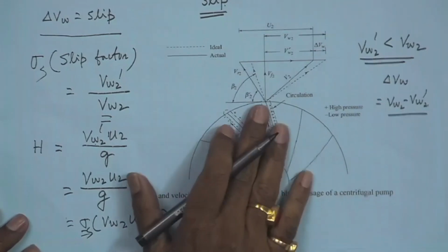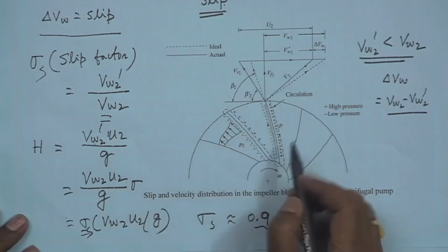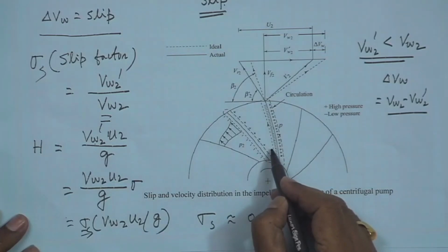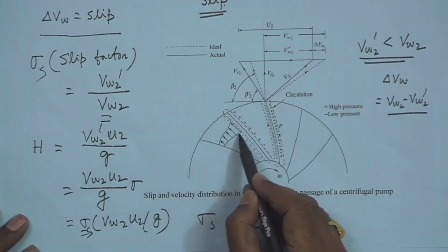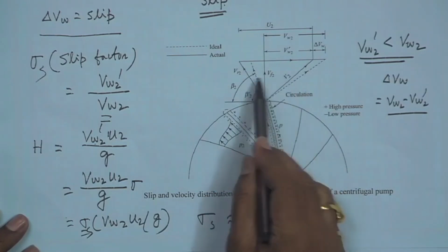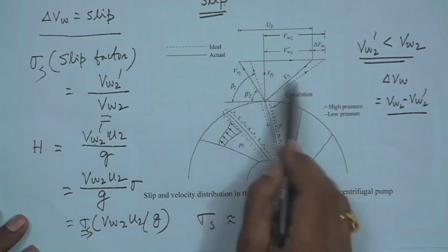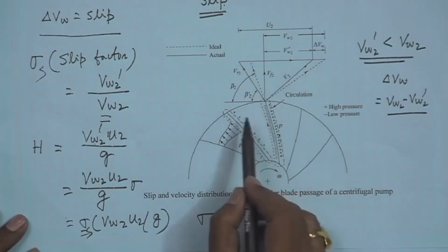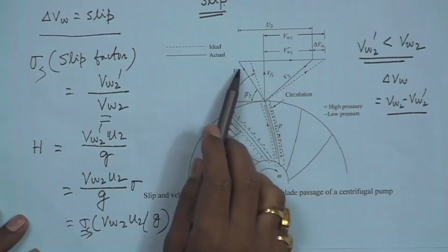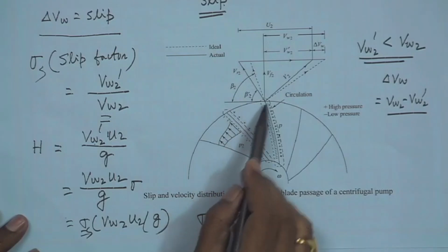This is because of the blade curvature, which induces different pressures on the leading and trailing faces, and creates the circulation for which the velocity distribution becomes non-uniform and makes an alteration in the velocity triangle from that of the ideal one. It changes the direction of the relative velocity from that of the actual blade angle, for which everything changes.